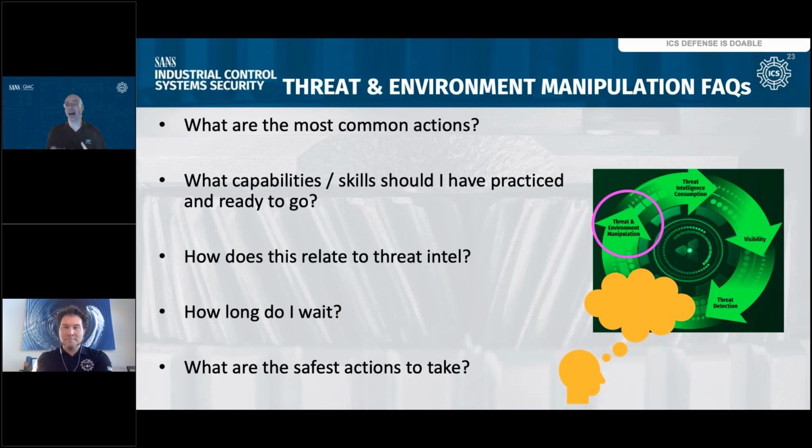So there are certain things like islanding we probably want to do early if we can do it quickly, easily, without impact. But the safest action is to collect information. If you have the ability to collect information, watch and learn, that's going to be your safest. And then what's next most safe? Something you have practiced and documented and approved and authorized. And finally, higher levels. Again, level 3, you're not going to have as much direct harm or risk to the process. So that's another good place, because that's probably where your attacker has started. That's another safe zone, or safer zone.